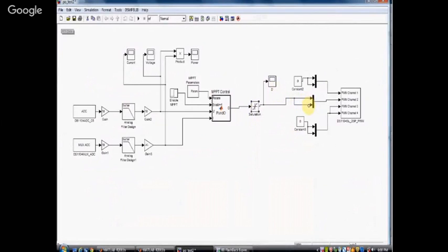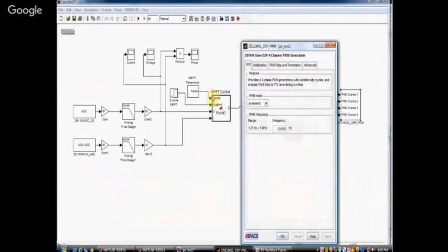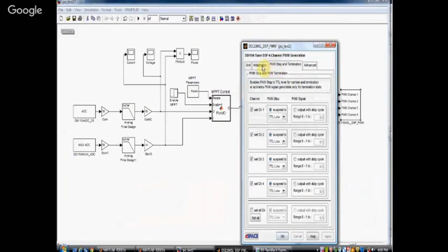Okay, and this PWM, I've already told you, we are just giving the 0 to the other ports, and thus PWM is given here. And in PWM, you can just see the frequency setting. While doing the experimentation, we did it for 120 kilohertz also. So that was a video which we recorded. We did it with different frequencies. So this model was for 120 kilohertz, which we recorded.